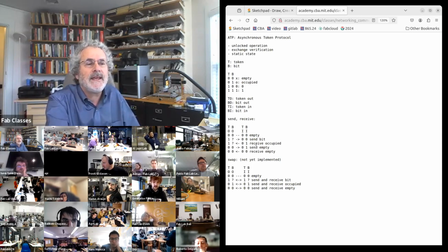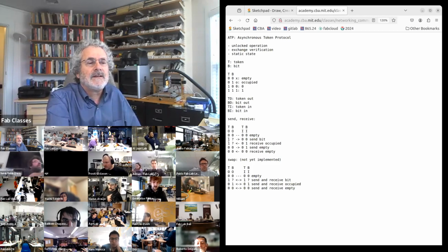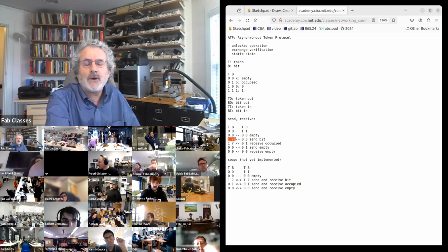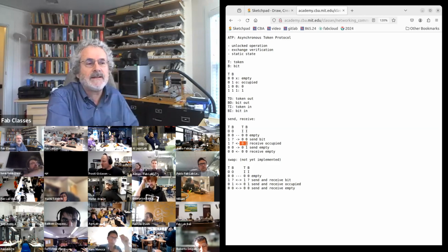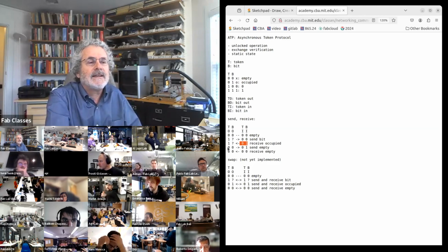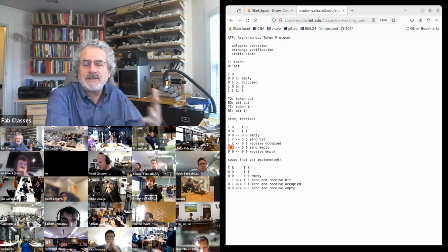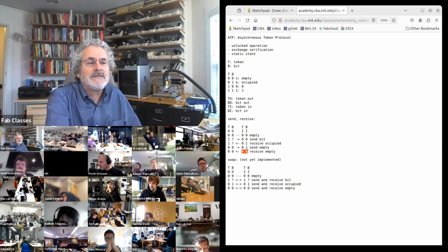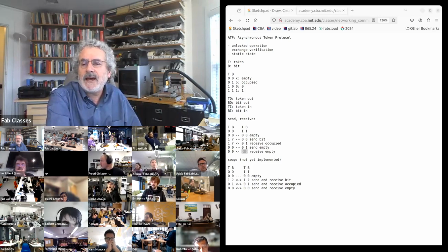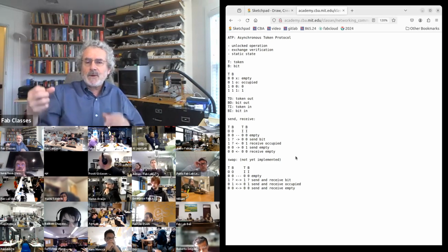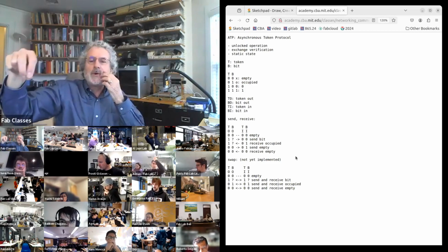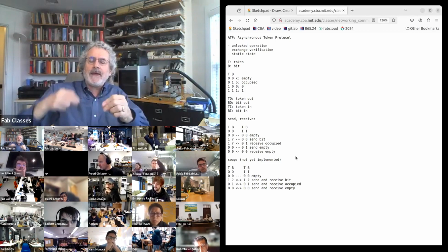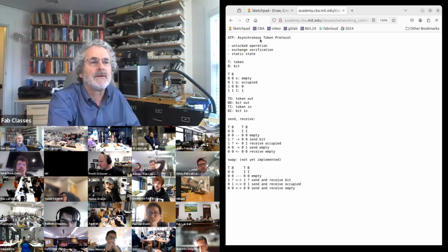And so the way you exchange data is the sending side says, I have a token, and puts up the data. The receiving side, by saying I'm occupied, says I've accepted your data. The sending side, by eliminating the token, says you've taken my data. And then the receiving line saying I'm empty says I've accepted it back from you. And so think about this like a checkers piece moving on a board. The data is like a token. I'm passing a data token to you.